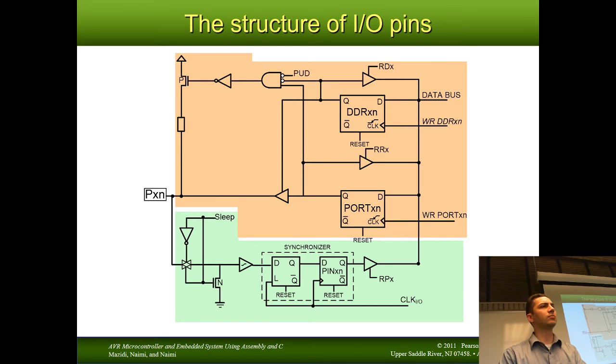First thing I want to call attention to right in the center, that symbol. Remember what that is from Digital Logic? Inverter would have a bubble on it. It's a type of buffer. It's a tri-state buffer. Tri-state buffer basically turns this into a magical switch, right? If we are enabled, this will act as just a wire. If we're disabled, put a 0 here, this acts as an open. It will not be connected. Now that makes a lot of sense if you look at where that enable comes from. It comes from a flip-flop labeled DDR.